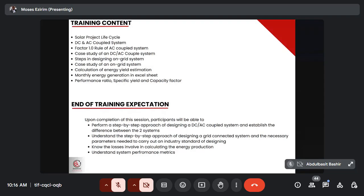All right, so once that is identified, then you proceed to the site to do your assessment. With your assessment, you do a lot of things. You'll be able to do your energy load. That's the main thing, because what you want to power is the load. It is the load that is actually leading to high costs. So that is the first thing that you need to do. You need to do your logging. That's the energy audit, to know what the customer load profile is, because what you want to bring in is solar, and you know that solar only operates during the day.